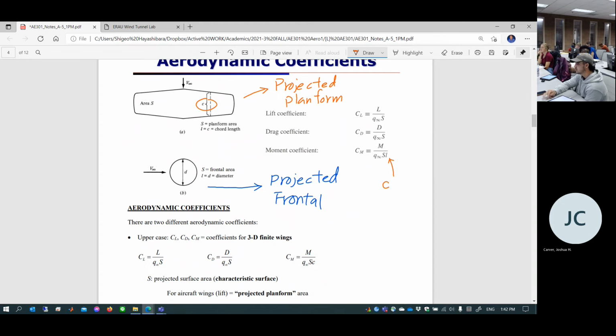Okay, anything else? Go ahead. For our drag producing device, what if instead of being a circle, it was like a brick where it has 2 dimensions associated with it? Still projected frontal area. That's right. Now, this length is questionable. I don't know what it is. It depends on the type of device you're talking about. It's usually diameter, if it's this kind of thing. Suppose it's a parachute, I don't know, it would still probably be the diameter.